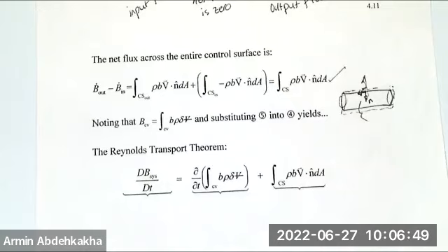but what about momentum? If the flow comes in with a higher velocity and goes out with a lower velocity, and also because of the shapes that you have inside of the control volume, or because of the vortex of the flow or circulation of the flow, then the momentum also changes, right? So you have three things. The flow comes in with a different velocity, goes out with a lower velocity. Then you have to add up the momentum inside of your control volume.